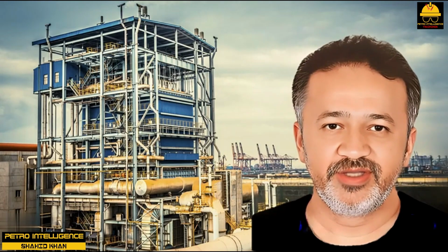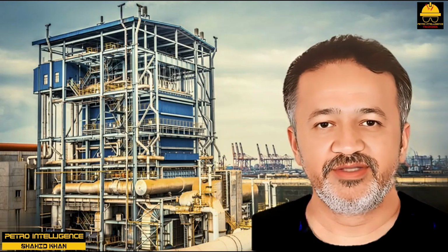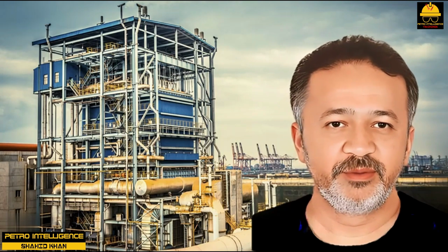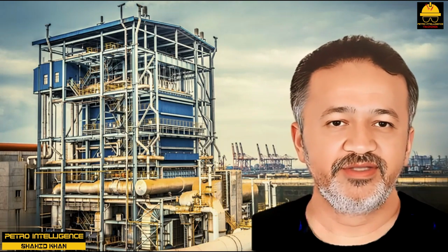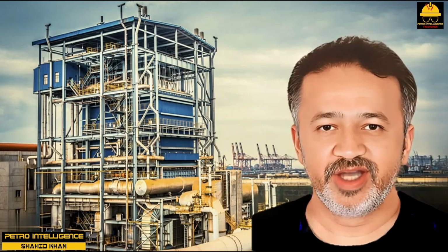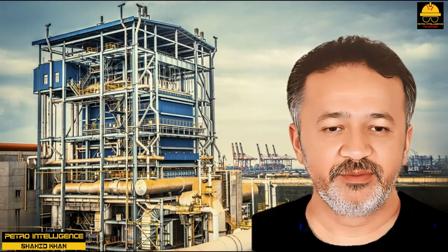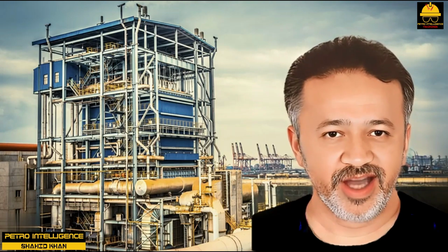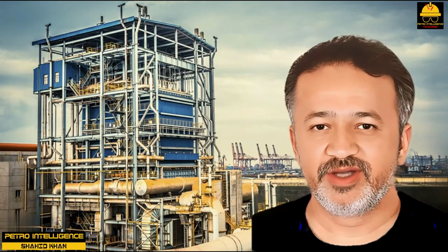General problems and concerns with twisted tube exchangers. The main concerns seem to be, is it going to plug up, and are we going to be able to clean it? The answer is that in general people find it is possible to clean both the shell side and tube side following manufacturer's guidelines, time period and method, and using fairly standard cleaning equipment.